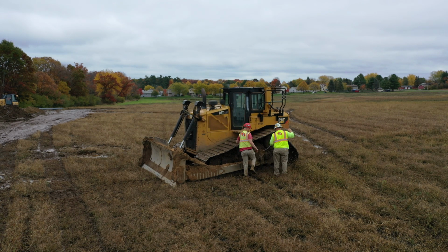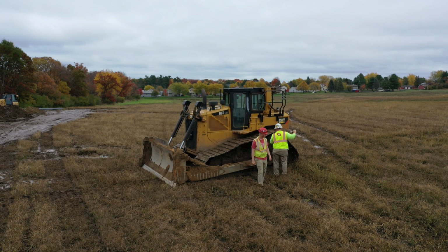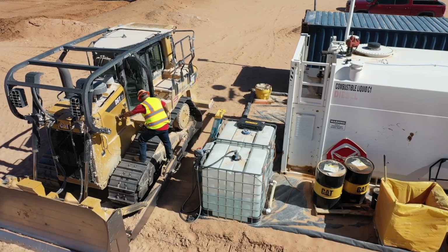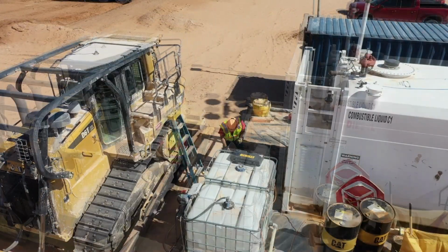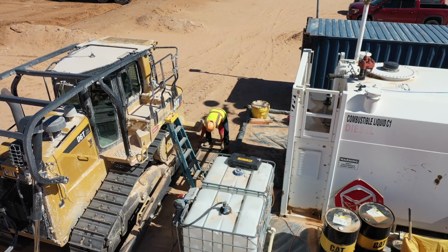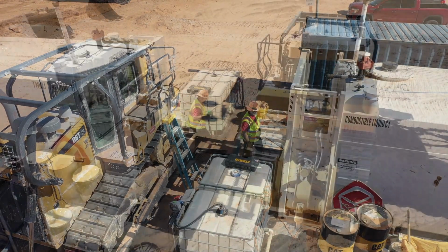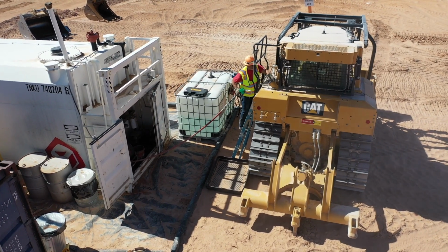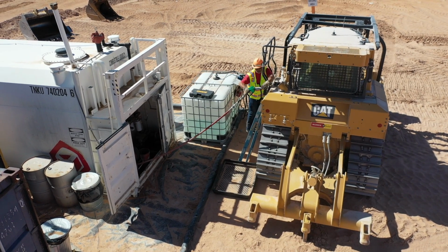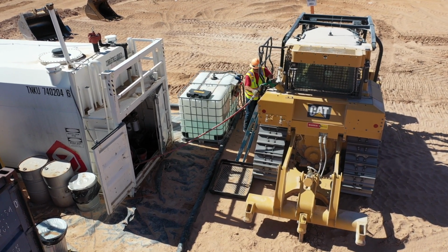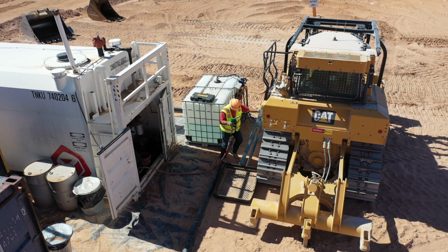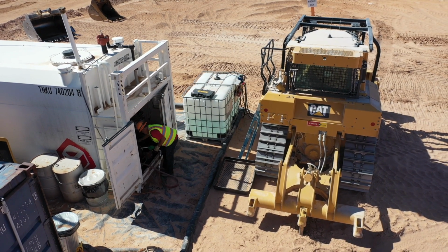Always use 3 points of contact when dismounting the machine. Clean tracks off at the end of every shift. Fueling and spills. Shut off the engine while fueling. No smoking. Be aware of slip and trip hazards. When parking at the fueling area, ensure spill mats are on the ground between the fuel tank and equipment to catch any spilled material. Place any spilled material, creating contaminated soils, immediately into a containment device and document on OHSEF 14, environmental spill or release report, or other form as required by the worksite.